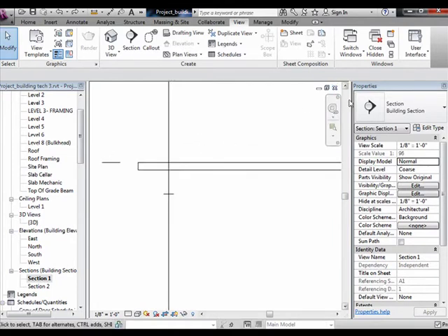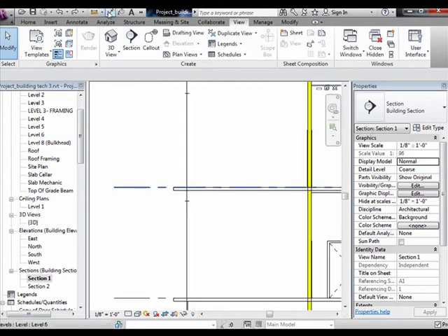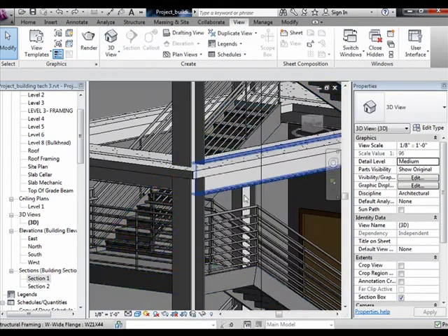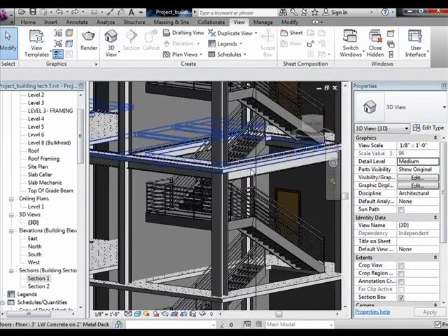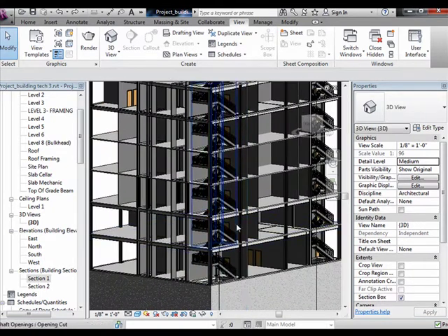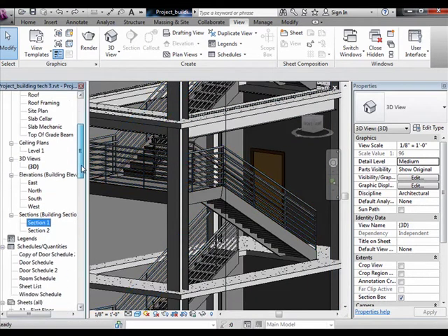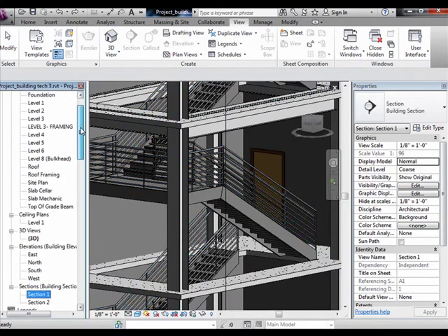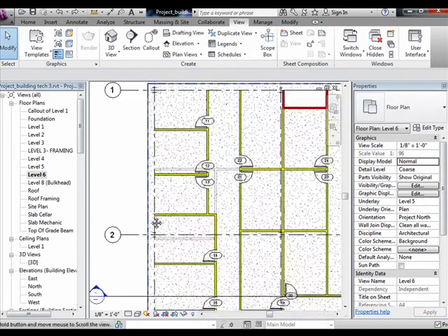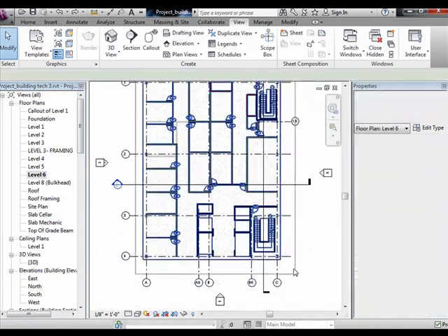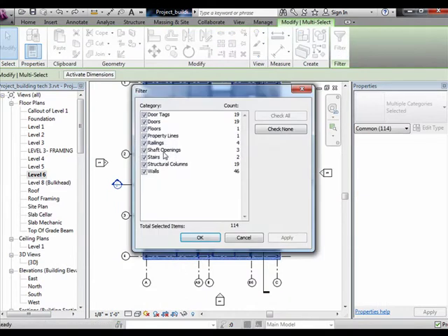And you notice sometimes if you can't select something like a framing in one view, use other views. For instance, in here, some of you had difficulties. I think you had a difficulty selecting framing from plan view. So like, let's see, we're on 1, 2, 3, 4, 5, 6th floor. So that framing is on the 6th floor and it's incorrect. So I'm going to go to the 6th floor from Project Browser, level 6, and just drag it, filter, and see, I don't see my structural framing.